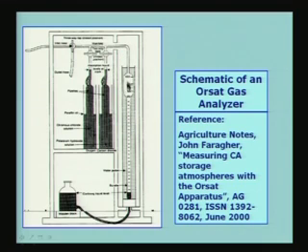So, when it has gone into the reagent flask, the carbon dioxide will be absorbed. So, whatever percentage of carbon dioxide is there in the sample will be absorbed, and therefore, what comes out is only the rest of the gas. So, what will happen is that when you bring it down, this level will go to a higher level, and of course, this will also be at a higher level, because the volume of the gas will now be lower by the amount of carbon dioxide which was present in the sample, which has been absorbed by the reagent in this vessel.